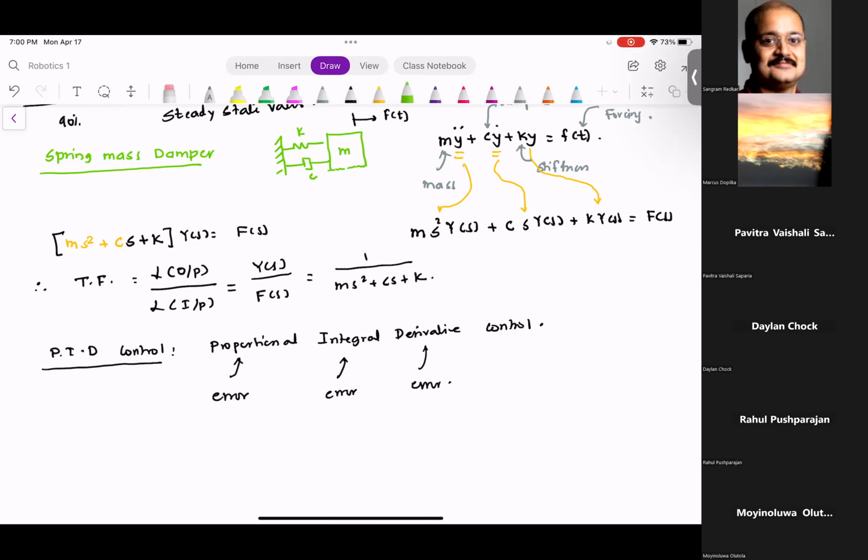So what that means is, say you have a system dynamics. I'm going to give you an example. Say m x double dot plus c x dot plus k x. And I want to add a controller term to it. So I'm going to add this k hat term to it. This is kind of a controller term.